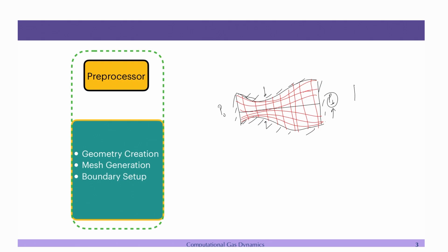This is very similar to, for example, what we had in the shock tube. You had something on the left, which was some pressure and density, and something on the right. If you want to solve it in 2D, it will be like this. If you want to do 3D, it will be like this, and of course, for 1D you can write your own code. I would strongly encourage you to write at least one 1D code to solve simple problems like the shock tube. You can use your favorite flux schemes and try solving it. This will give you confidence that you understand the nuances of CFD.